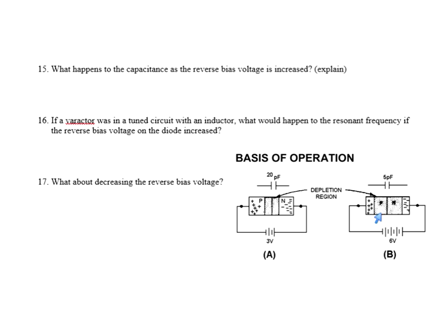Caught me off guard. Here, the plates are further apart. I'm going to have less capacitance because I have a higher voltage and a bigger depletion region. It is correct. Here, when I reduce the voltage on the cathode, the depletion region is smaller, and it looks like the plates are closer together, so this would be more capacitance.